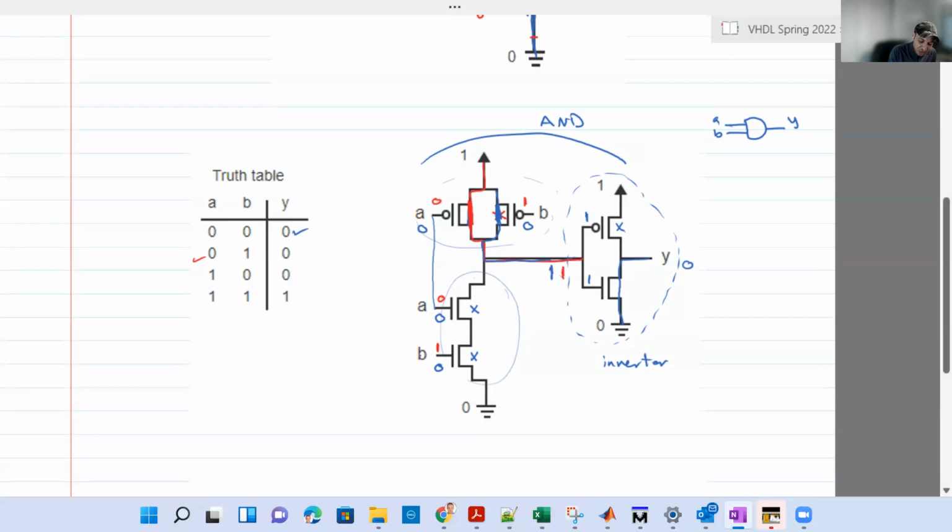You don't need even to consider the rest because it will be complementary as well. Let's check. So 0 at the NMOS, it's open. 1 at the NMOS is short, but remember, this is open. So you have a short circuit, then an open circuit. It's still open. There is no current that can flow. And again, here you have 1. This is an inverter, you will have 0.